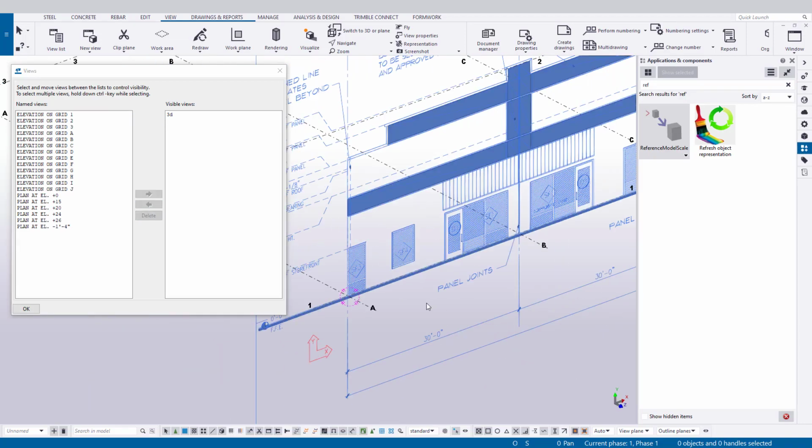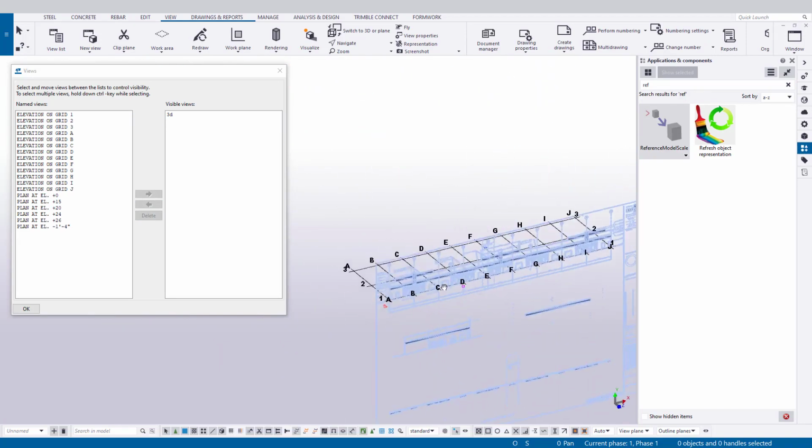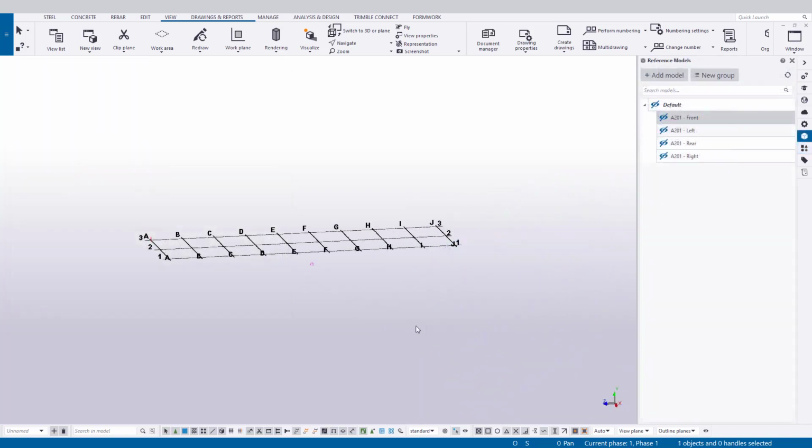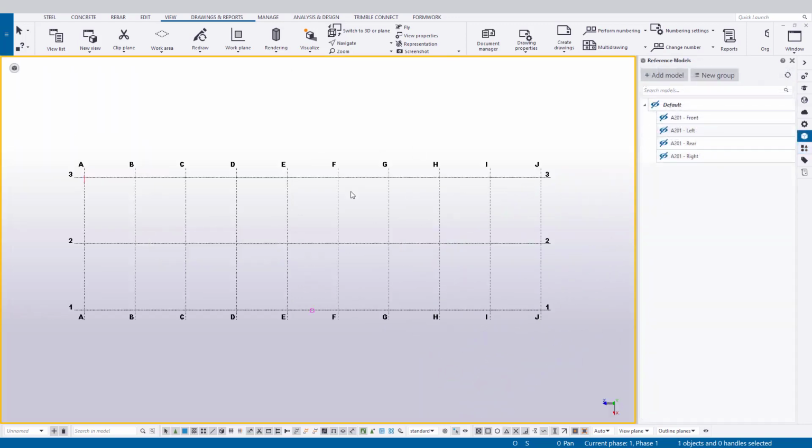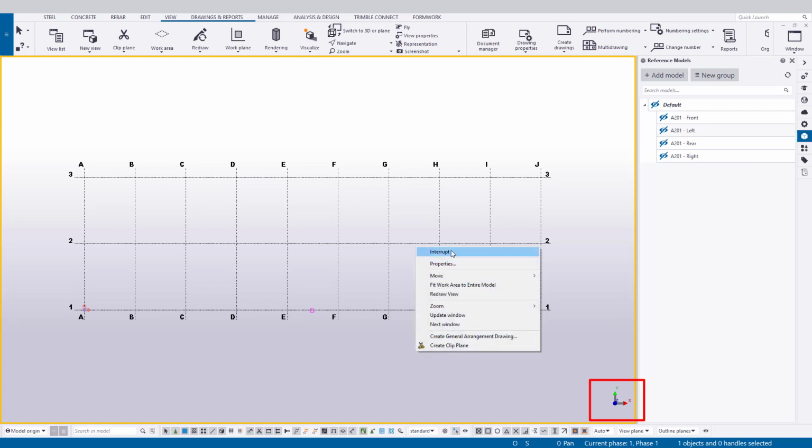Once you're done inserting your vertical PDFs, ensure to open up your plan view or 3D view and snap to plane so it's not rotated, and set the work plane parallel to the view one last time. This will ensure that your work planes are set correctly back to the normal XYZ configuration. You may now use your PDF references in the elevation views as needed.